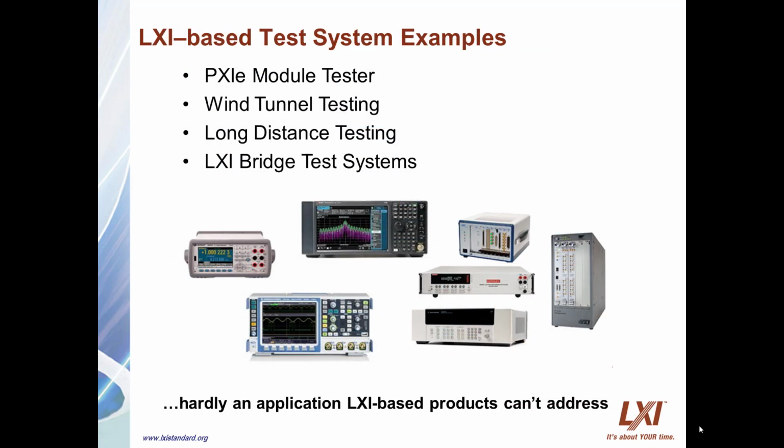Here are the test systems covered in this presentation. Just from these images, you can determine that LXI covers not only proprietary implementations for signal generation, signal measurement, and switching, but you will note the presence of VXI and PXI modules through the use of LXI bridges.